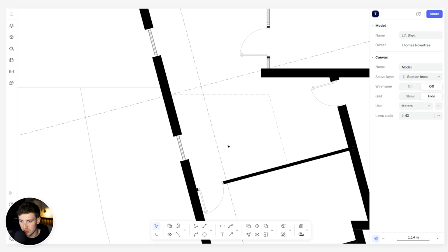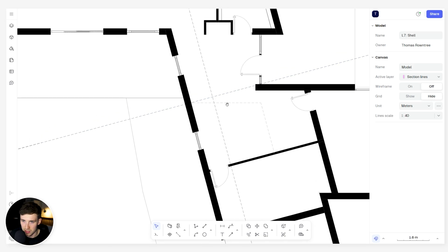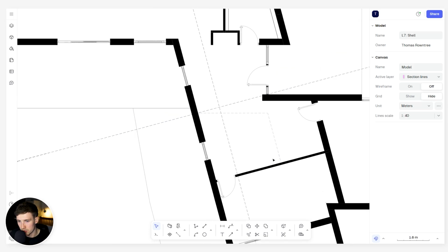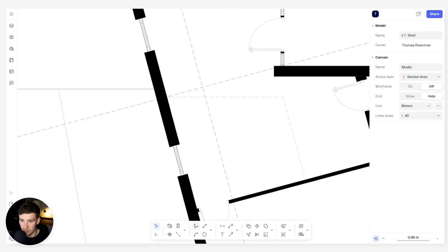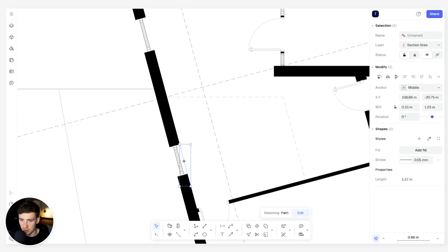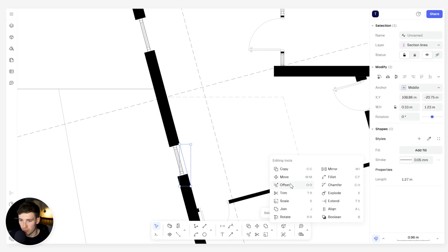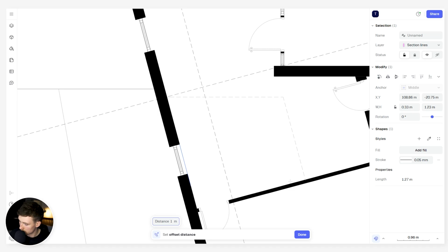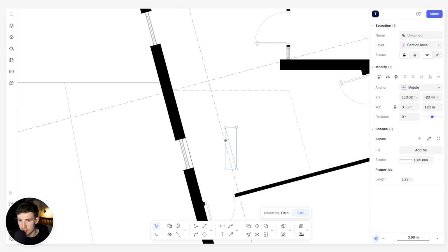we obviously have a door that we have to be sensitive to at this point, and as you enter this space, you probably don't want to butt the stair right up to that back wall. Instead, we could have it maybe central, so we have a bit of a feature. So if we draw a line along here, we then offset that, so we probably want that to be 1.2 meters minimum really. If we drop that there, the stair could start there.